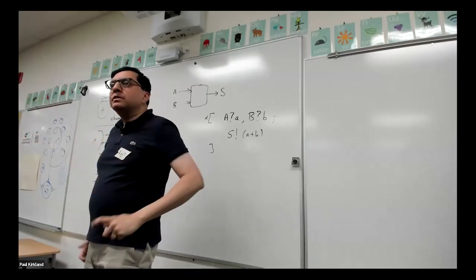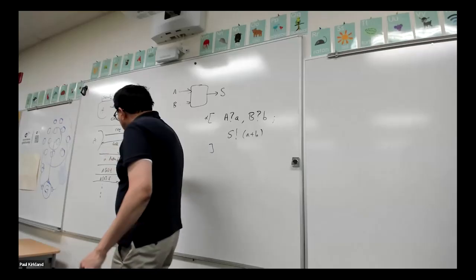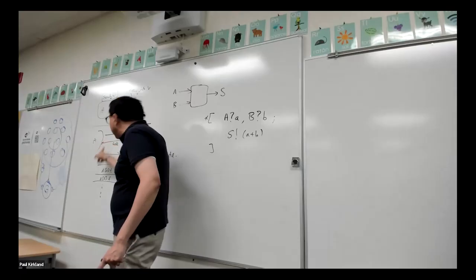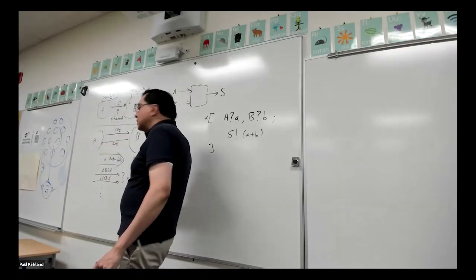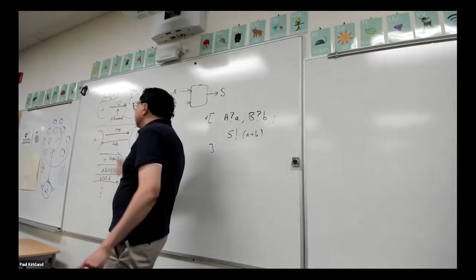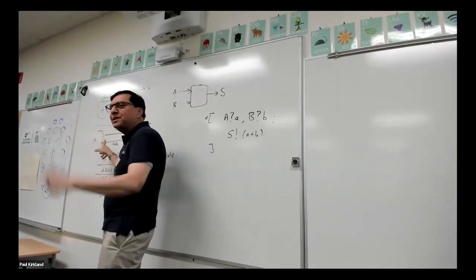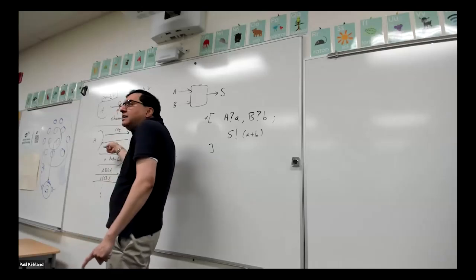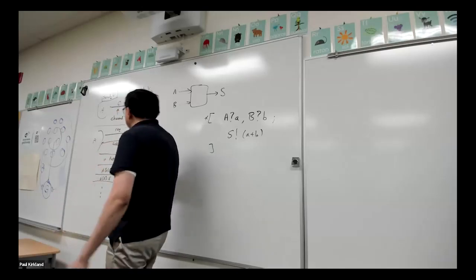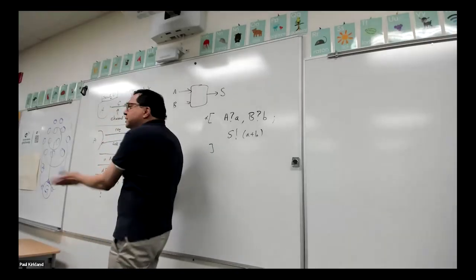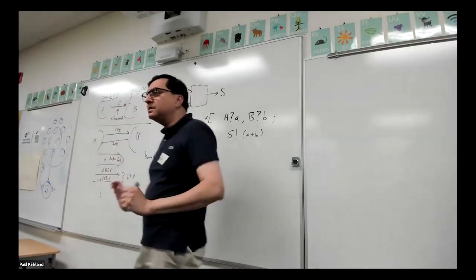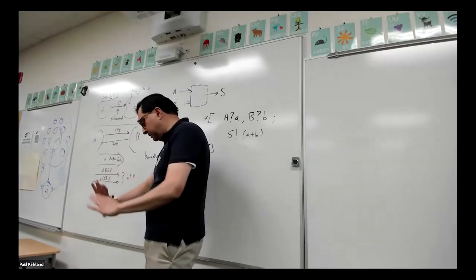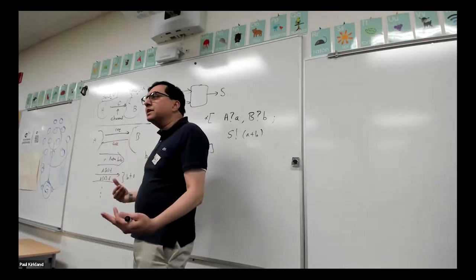Just to clarify, the receiver makes sure that it has received either true or false. That's right, and then it raises the acknowledge. You can't acknowledge until you have received all the bits, so you wait for all the data to be ready, then you raise the acknowledge. So it's a full protocol. It's like an AND circuit, a completion circuit. You need a completion circuit to generate the ACK, you can't use timing. Then you reset, and you reset. That's the 4-phase version. There are 2-phase versions, et cetera. Is that clear? So this is a delay insensitive protocol. That's basically what ends up happening.